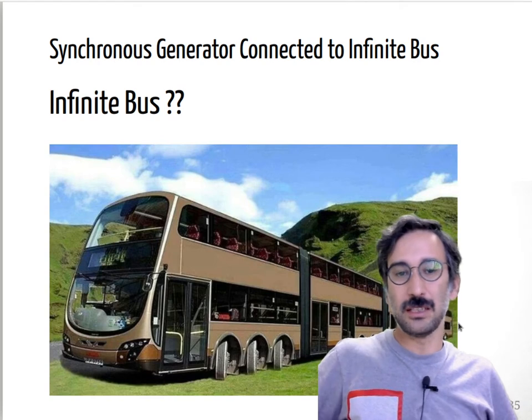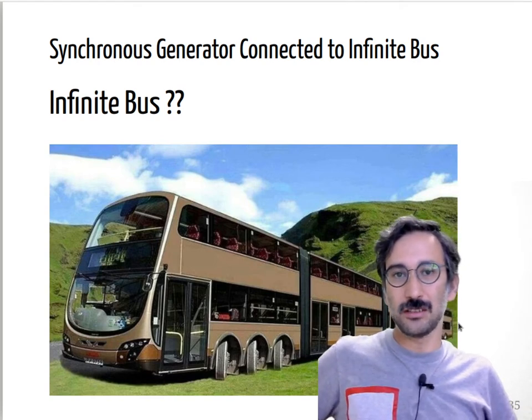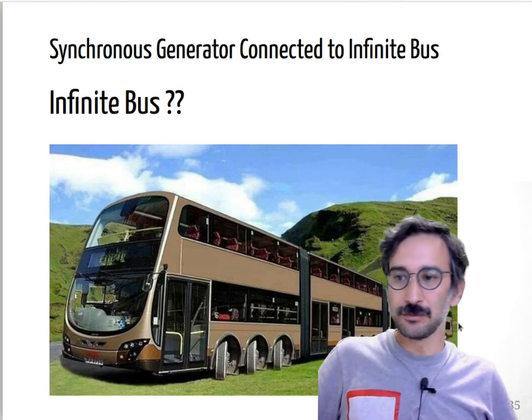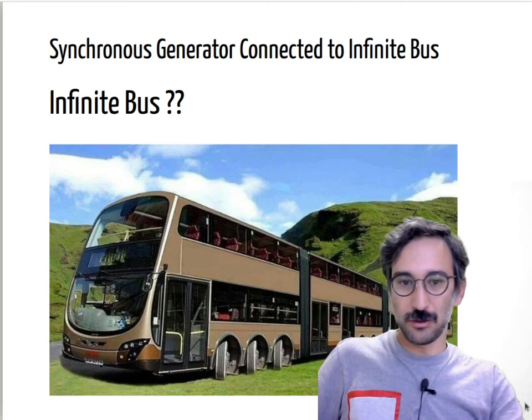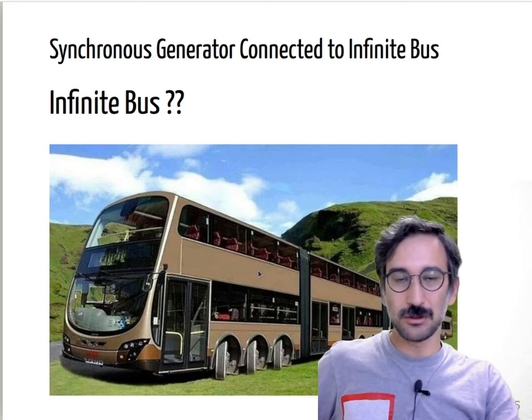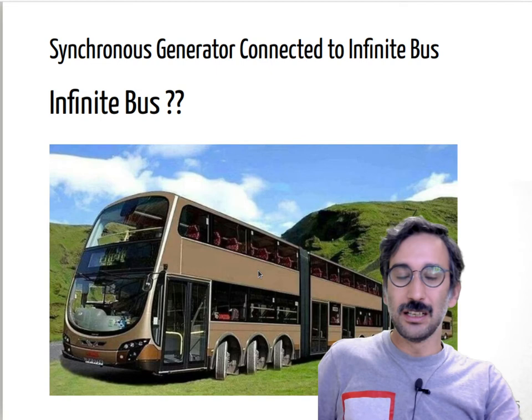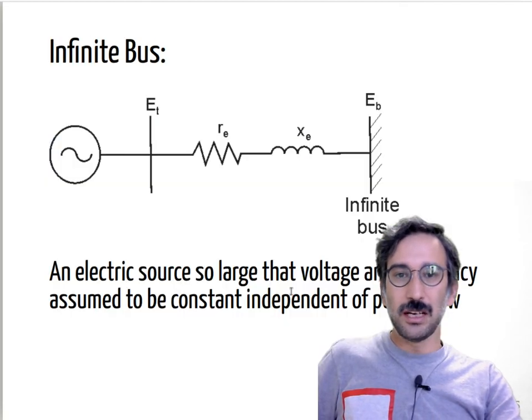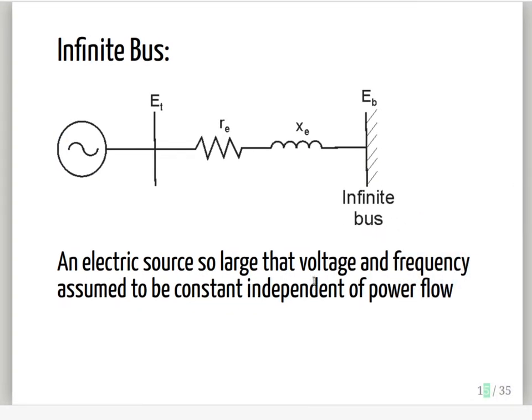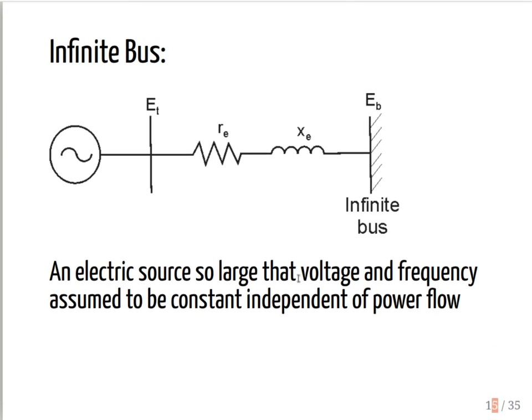So infinite bus is a term you will hear a lot in the power engineering area. Of course, it is not that kind of bus, or a metro bus like one of the ones in Istanbul. Infinite bus by definition is an electric source so large that the voltage and frequency are assumed to be constant, independent of power flow.